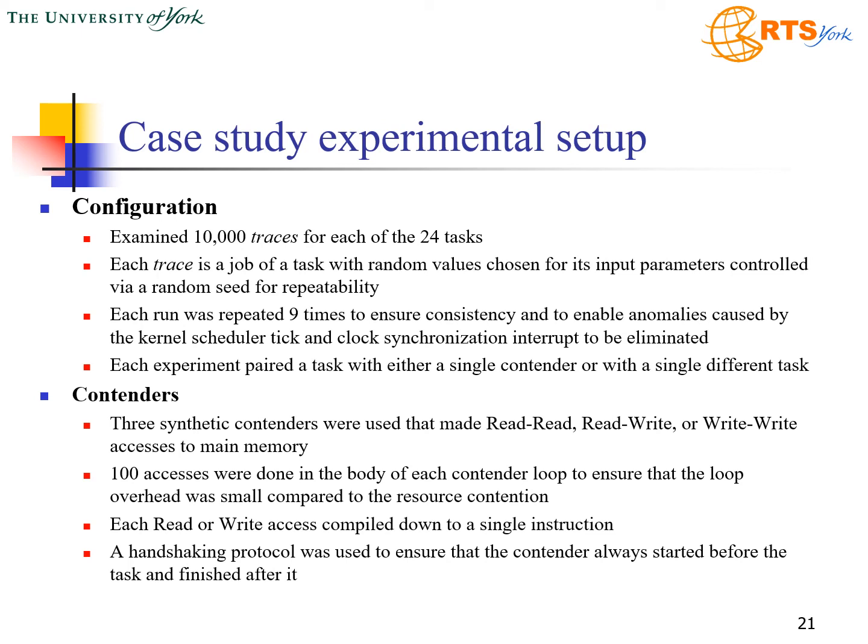Our experimental setup examined 10,000 traces for each of 24 tasks. Each trace is a job of a task with random values chosen for its input parameters. And each run was repeated 9 times to ensure consistency and to enable anomalies to be eliminated that were caused by the kernel scheduler tick and the clock synchronization interrupt.